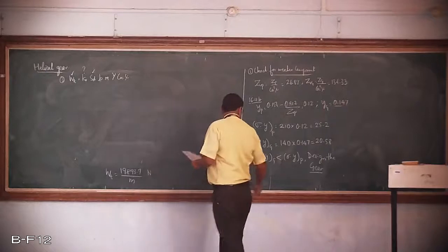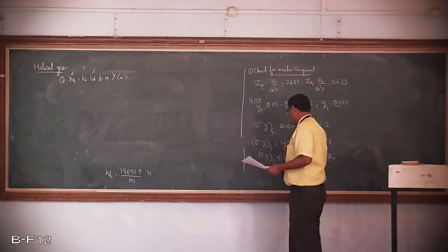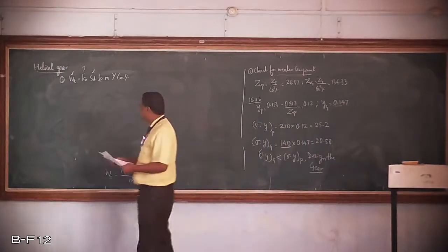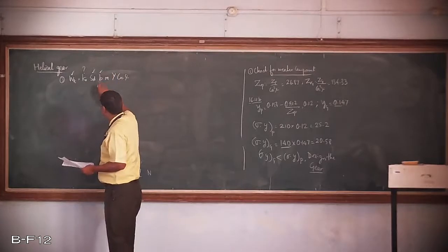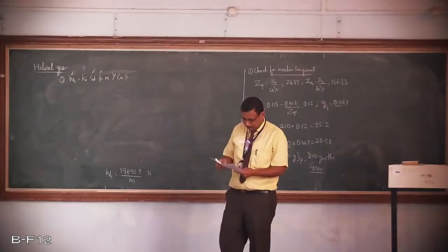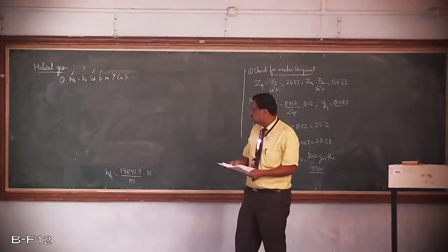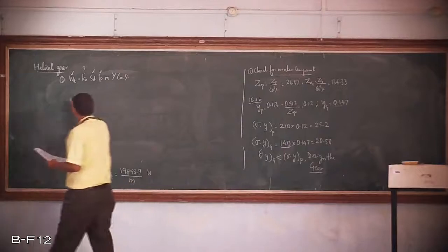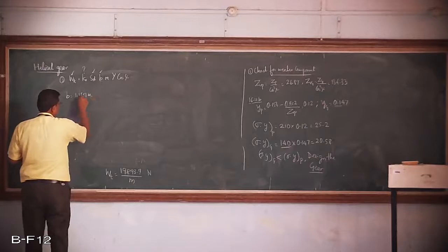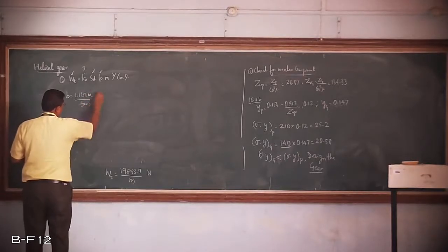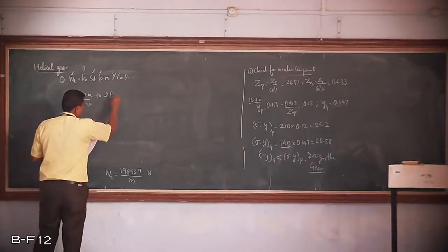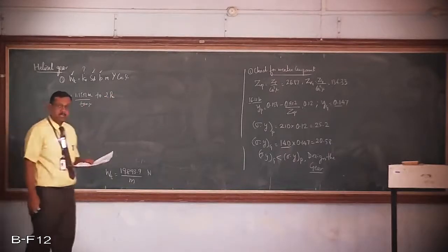The gear is weaker here. Therefore, as the gear is weaker, the static strength for the gear is 140 megapascal. Therefore, we know this value. B, the face width: the range is given. If you see equation number 16.26, the value of B is 1.15 times pi m divided by tan of phi, to 2 times px. px is the axial pitch.